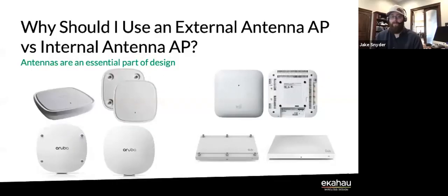Well, I'll kick it off. For me, it comes down to the things you're trying to achieve. If your requirements are fairly low, integrated Omni antennas are great. They're easy to deploy, but if you start asking more and more out of your wireless network, when you start increasing the density of access points and users in a physical space, suddenly controlling where that RF goes is super critical to being able to do more.